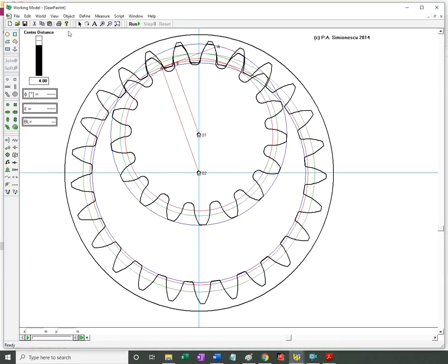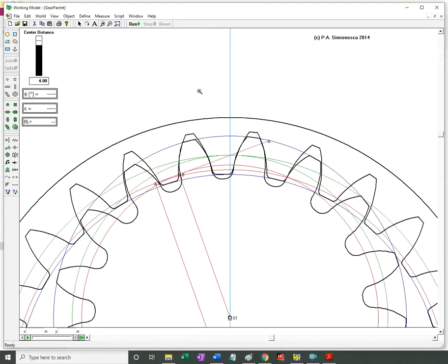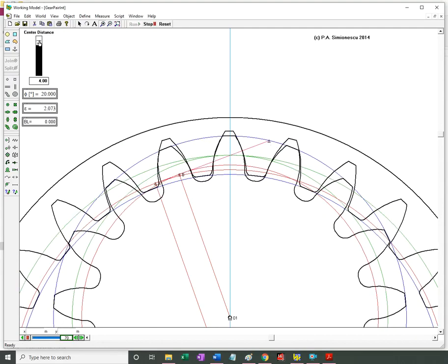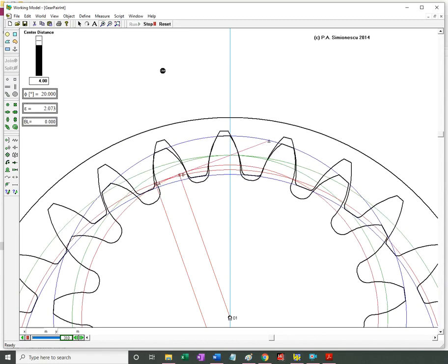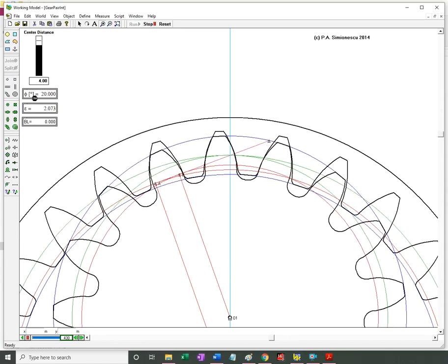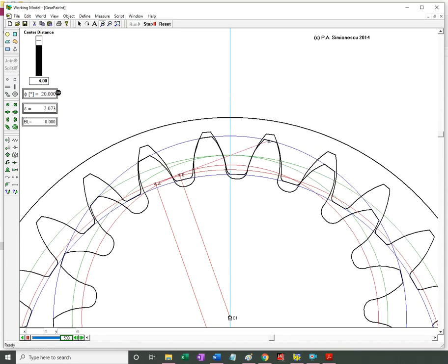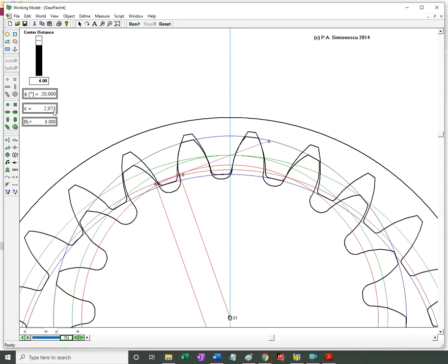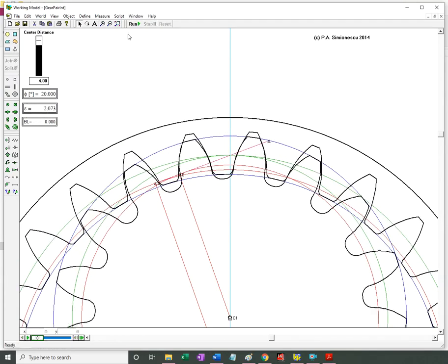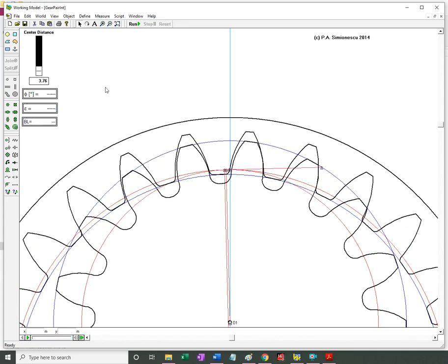I have the case of internal gearing, also illustrated with a simulation, and let's see, does it respond on the fly? Sometimes it does. So pressure angle 20 degrees, zero backlash, large contact ratio. If I reduce the center distance now because I have internal gearing, I have some backlash.